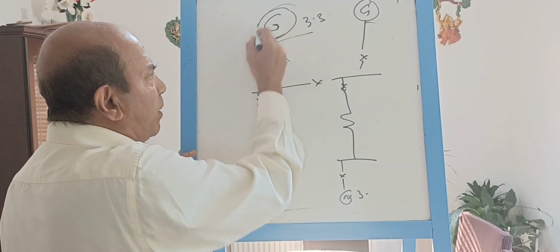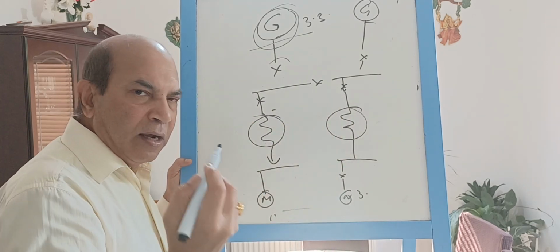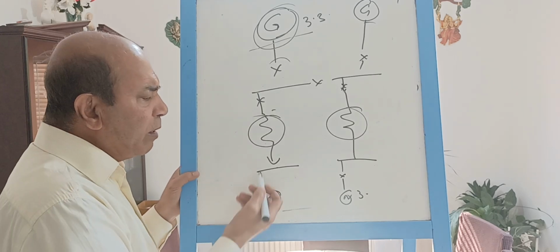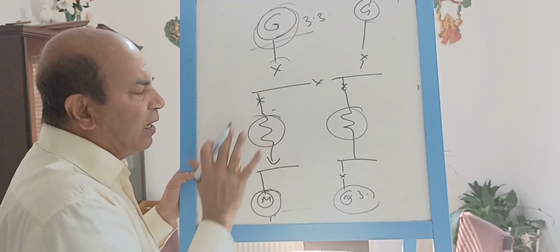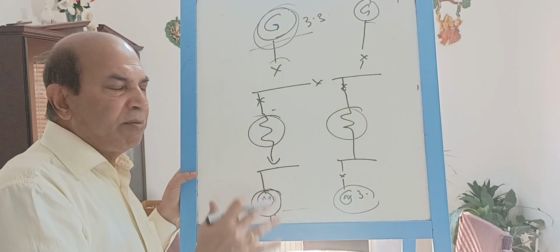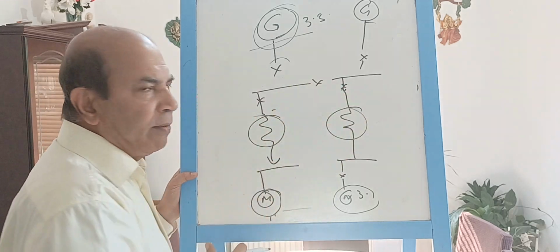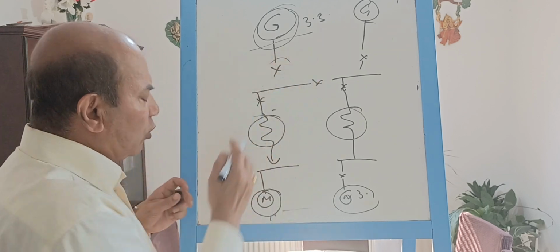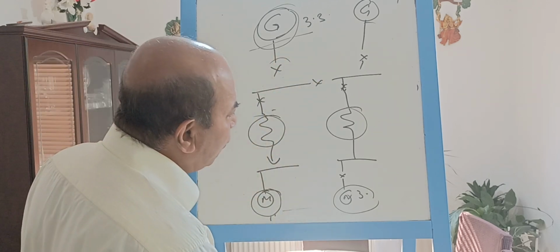We know the ohmic value of the cables; we can get it from the cable catalog. Motor impedance in ohmic value, maybe we can get from the manufacturer. So in this type of circuit, where the AC system has only a single voltage, we can use the ohmic value which we discussed. But if it is multiple voltage, it is not possible to calculate in ohmic value. In that case, how will we represent this?